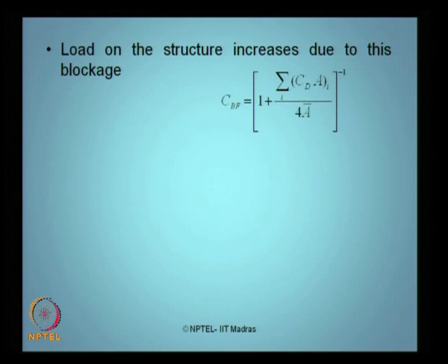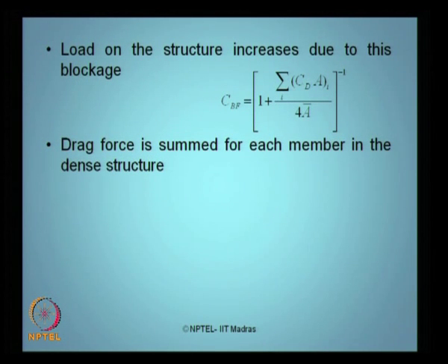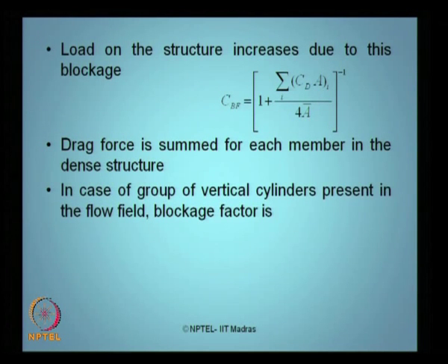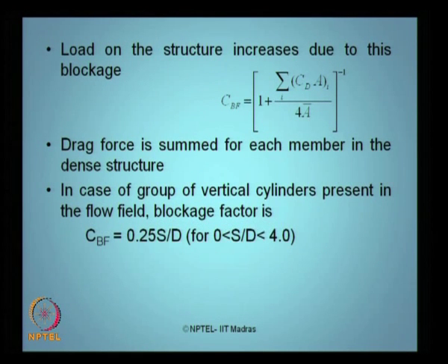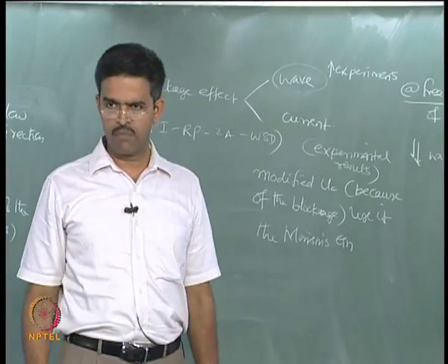So the load on the structure increases because of this reduced velocity due to blockage, and we compute this blockage factor as CBF as given in this expression, where the drag force on each member is summed up separately and then arrived at for the influence of the blockage factor on the structure. The blockage factor will anyway enhance the load because of the wave action, but there is no experimental evidence thorough enough to verify this fact, therefore this is not accounted for in the design at present.